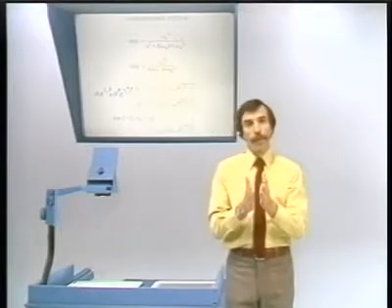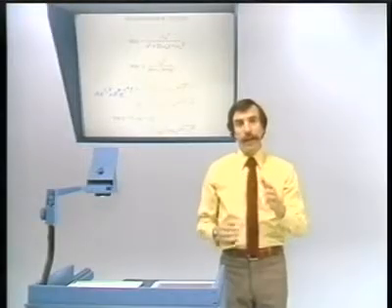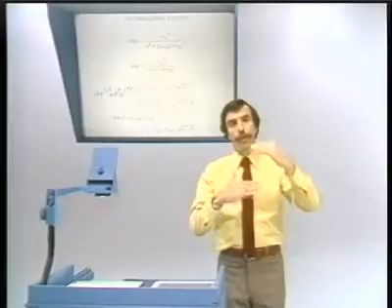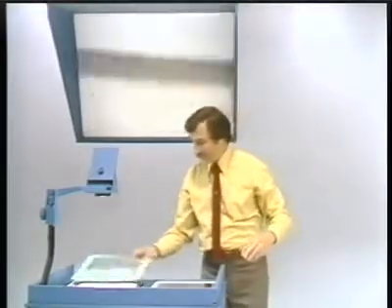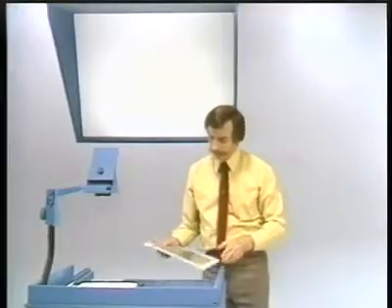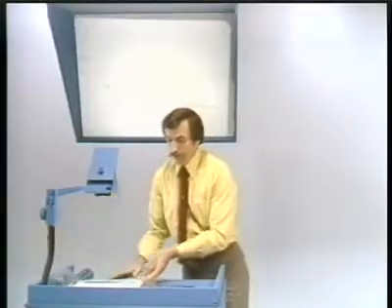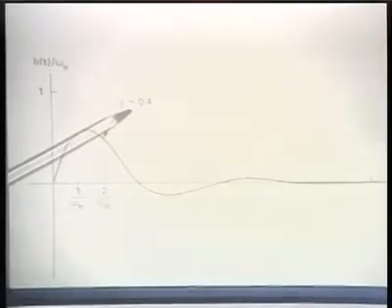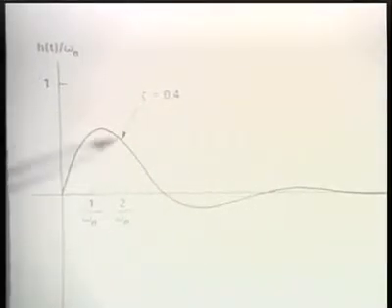In the time domain, the real part of the poles has gotten smaller, and that means, in fact, that in the time domain, the behavior will be more oscillatory and less damped. And so just looking at that again, here is, in the time domain, what happens. First of all, with the parameter zeta equal to 0.4, and it oscillates and exponentially dies out.